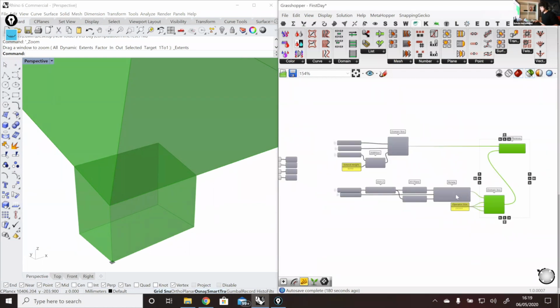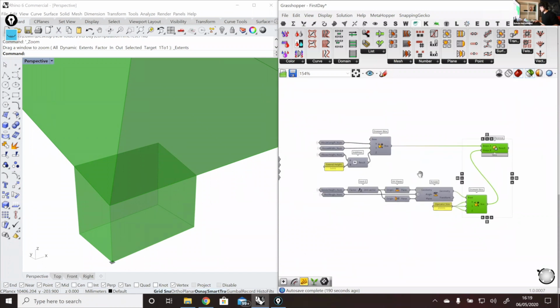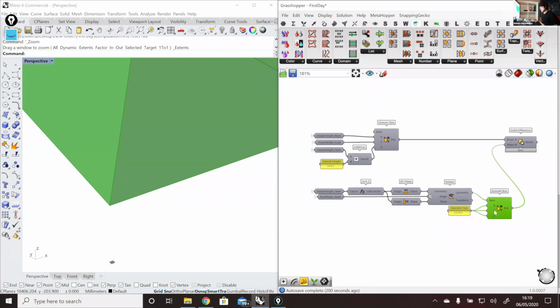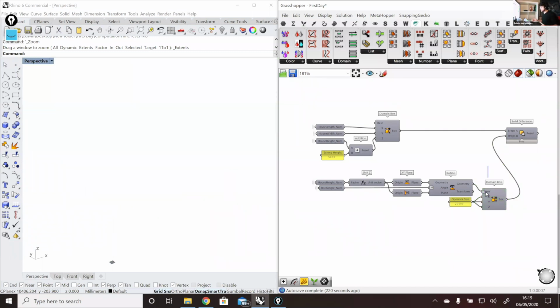Then we started to explode this component, but before that, I will first explain here. One of the things that we've seen over the years working with other Grasshopper developers is that they normally don't use all the inputs that some components offer. For example, this box offers a base plane, and X, Y, and Z domains for the size of this box. To keep this script compressed and organized, we try to always use all the inputs.